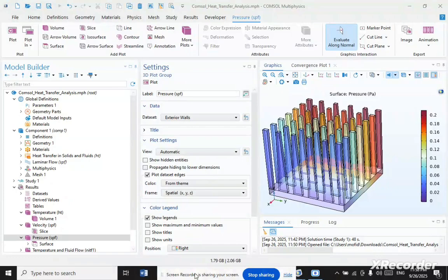The fluid flow characteristics in microchannels significantly differ from conventional channels, as shear and surface tension forces become more significant and the influence of gravity forces reduces. Channels having a size in the order of micrometer or millimeter are recognized as microchannels. Despite this, researchers identify channels as microchannels if their diameter falls within 100 to 1000 micrometer, according to the currently available literature.